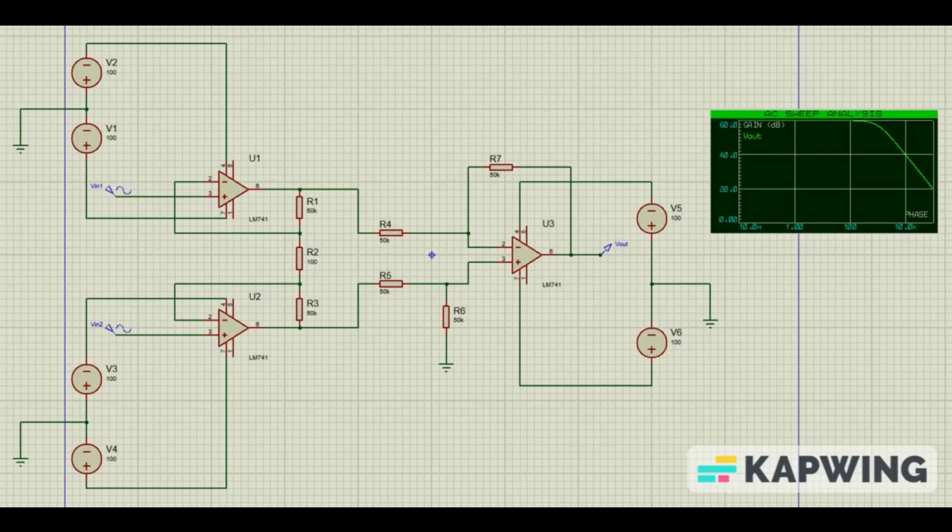So most ECG signals have a gain of at least 100 decibels. A circuit's gain is measured in decibels and is equal to 20 times the logarithm of the output voltage divided by the input voltage, as it was mentioned earlier. So we can calculate the ratio of output to input voltage in terms of resistive components by using nodal analysis. For our circuits, this leads to a new gain formula that includes components from both the band-pass filter and the amplifier. So in order to achieve a gain of 100 decibels, we need to select appropriate values for the resistor and feedback resistor components of the amplifier.